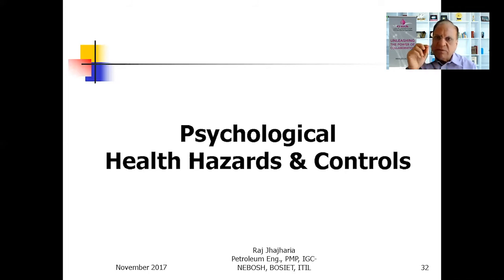And the other thing is that when these people come, they actually look at the body also, and they look at its strength and so many other tests they do. But these are indicators which are there on the extinguisher itself, and you can visually check it. Okay, sir. But in case of foam, if the foam has been kept in the extinguisher for too long, there is a shelf life of the foam, its effectiveness reduces and it needs to be changed. Even if the pressure is all right, because it has been kept for too long, the foam must be changed.